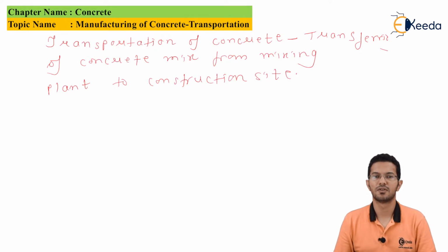Many factors determine which type of transportation is most suitable. Types and constituents of the concrete mix, size and type of construction, topography, weather conditions, that is temperature, humidity and wind speed, location of the batch plant, and cost are all taken into consideration when choosing a mode of transport for your concrete. If you choose the wrong mode of transportation, your concrete could be segregated, which would make it useless. Therefore, it is essential that adequate thought be given to the type of transportation you actually need.